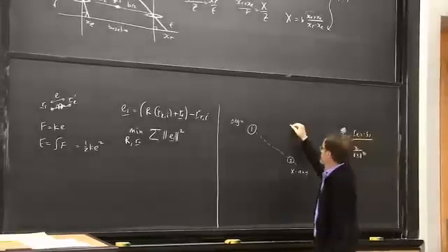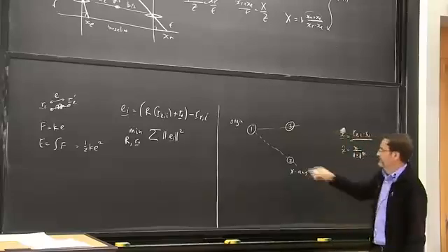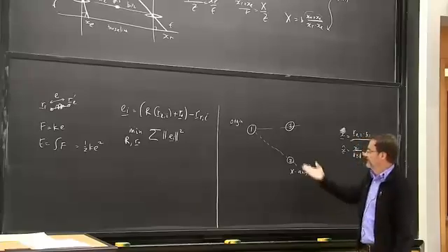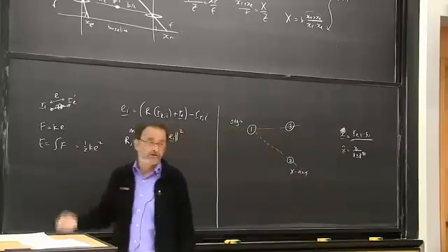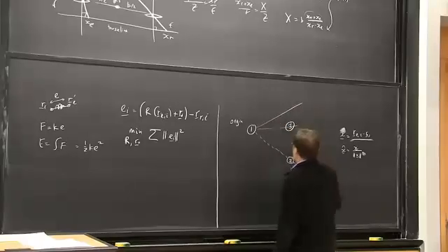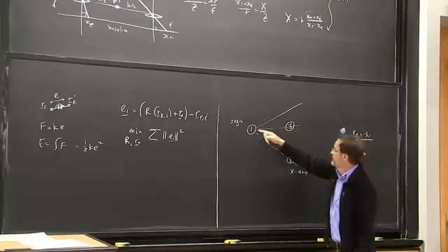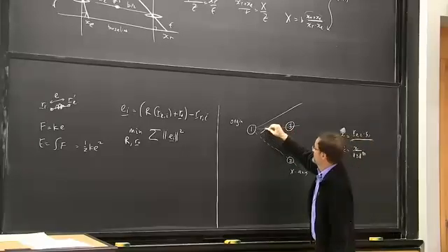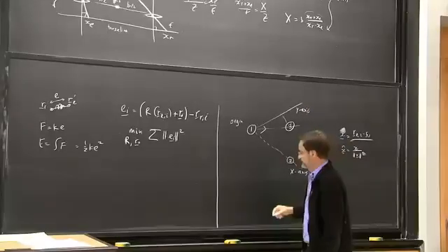Now we take a third point. Now we can't connect these up and say, okay, that's the y-axis, because then the x and y-axis won't be perpendicular. But what we can do is decide that the plane defined by 1, 2, and 3 is the xy plane. So we can certainly do that. And actually, based on that idea, we can just remove from the vector from 1 to 3 the component that is in the direction 1 to 2, and what's left is going to be automatically perpendicular to it, and that's the y-axis.